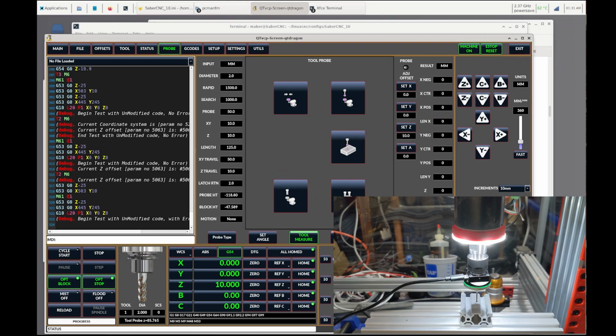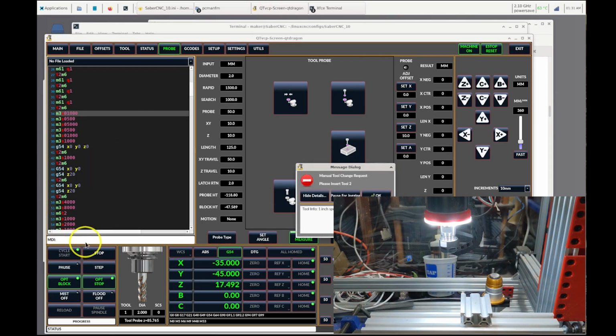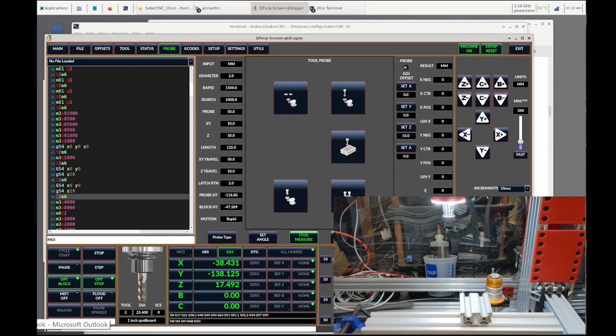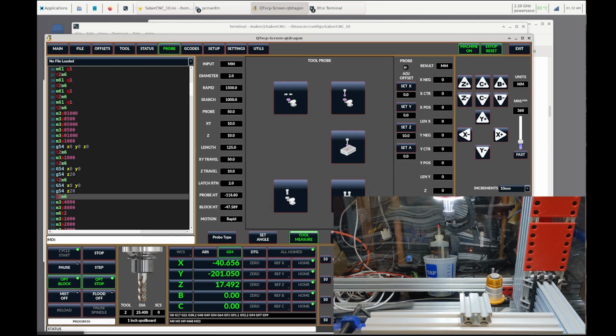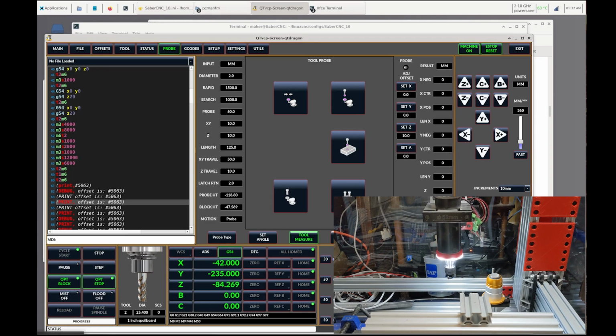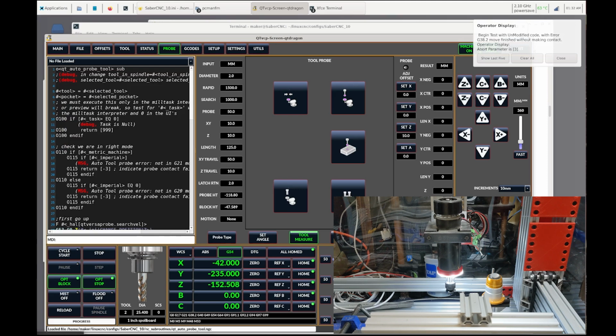The only thing we need to do here is perform the tool change. Okay, we're going to hit OK, and it's going to attempt to execute the tool change. But you'll notice that we're not over the tool setter. So once it begins the probe, it will find that it's gone 100 millimeters and can't find it. And so then we get the message, and it's pretty clear.